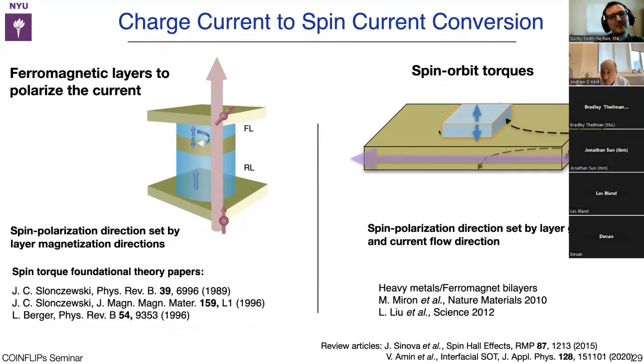So you gain that way, and you may gain in the speed. If you want to operate at, say, hundreds of picoseconds rather than nanoseconds, that would be the positives. And I'd say the negatives would be the increased area and maybe the increased complexity of the CMOS, more CMOS needed per bit.